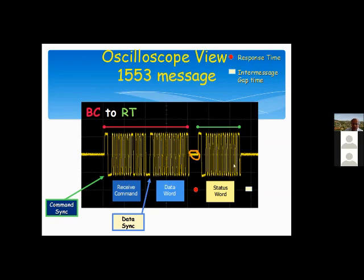In addition to which I see that here, the sync is going down, and here it's going up. Okay, so that means these are different syncs. If they're different syncs, then this has got to be a command, and the second one has to be data, because you're never going to have it in the opposite order. Commands are often followed by data. Data is never followed by a command. And in fact, data is never even followed by a status, because if an RT is sending both status and data, the status is going to go first, not last. Okay, so therefore, here's a command sync.